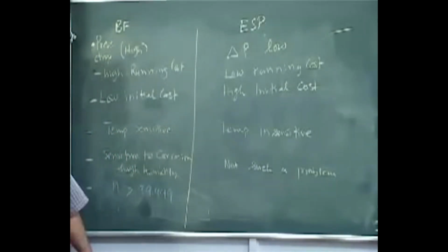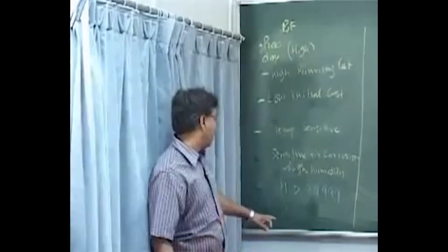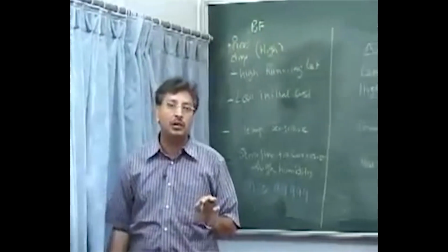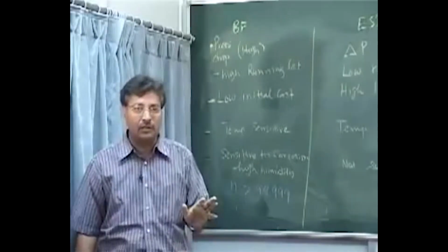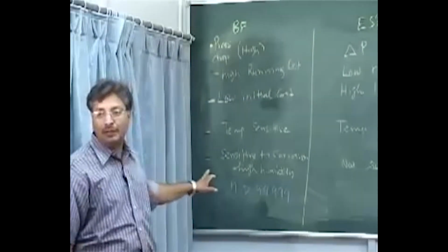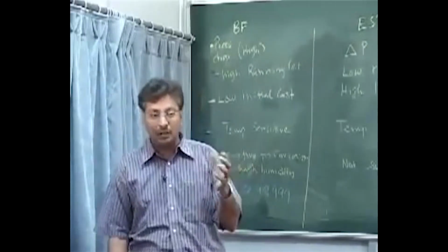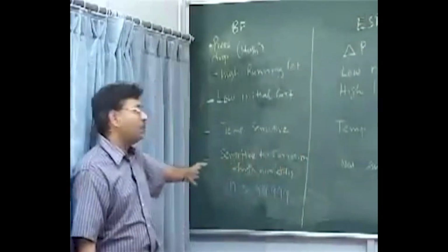Very good, Anand, practically everything is stopped. So the efficiency of the removal is very high. Whenever you are dealing with something most valuable, you will always use the bag filters. Suppose you are working in a gold processing unit and the gold is in the form of particles, you will not go for the ESP, you will put the bag filter.